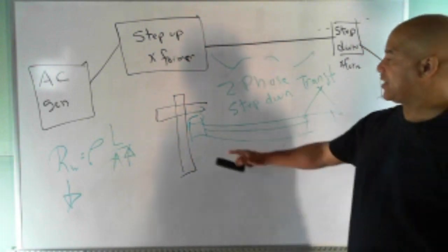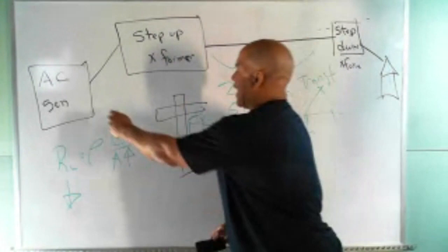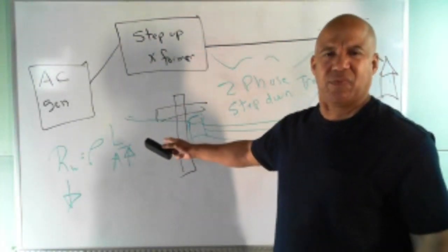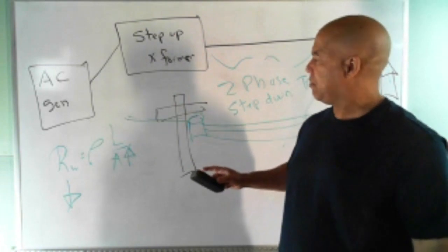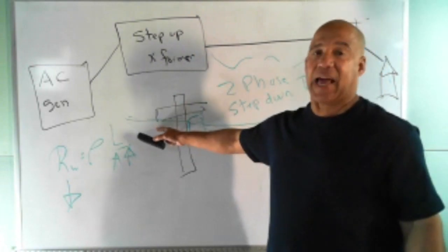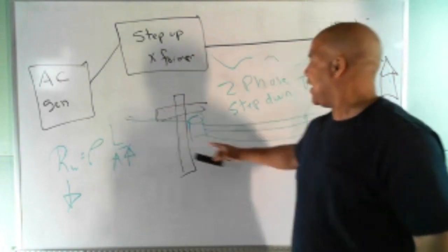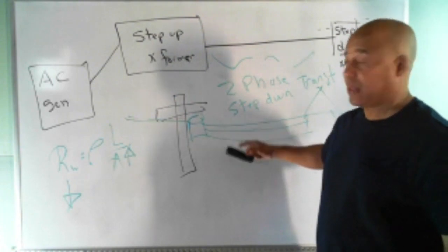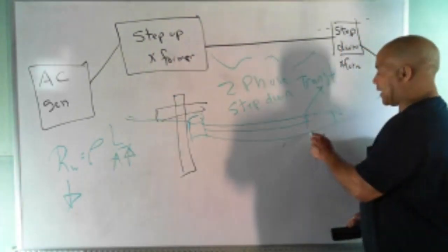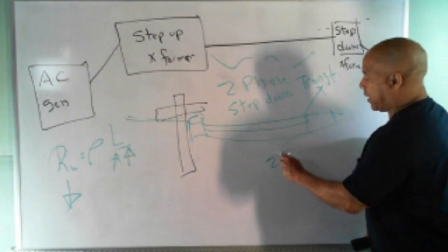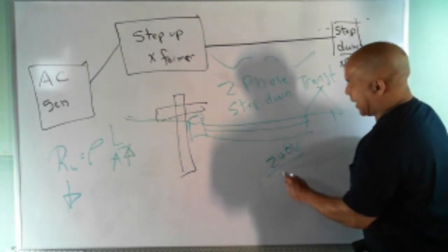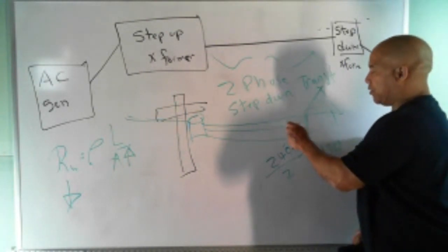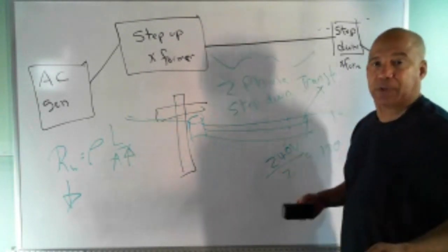So this steps it down from, I forget, on this side of the power lines, I want to say it's about 2,000 volts. I might be off a little bit, but it's a relatively high voltage, like 2,000 volts. It steps it down to 220, 240 volts AC. And then from that, in the house, they can split that 240 volts divided by 2 is 120 volts. They can use half of that. You know, your wall outlet puts out 120 volts.